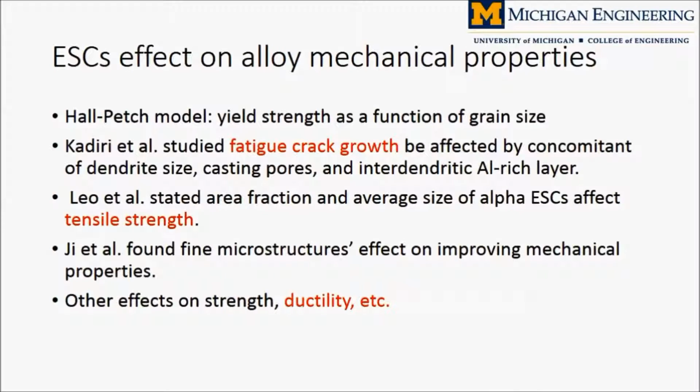The variations of mechanical properties have been found to depend on alloy microstructures, such as porosity, oxide skin, and grain size distribution. ESCs play a significant role in affecting fatigue resistance, tensile strength, ductility, and so on. For example, in terms of the Hall-Petch model, since ESCs show a significantly larger grain size compared to fine alpha-phase grains, ESCs would cause a remarkable increase of the average grain size and consequently should have a notable effect on alloy yield strength.